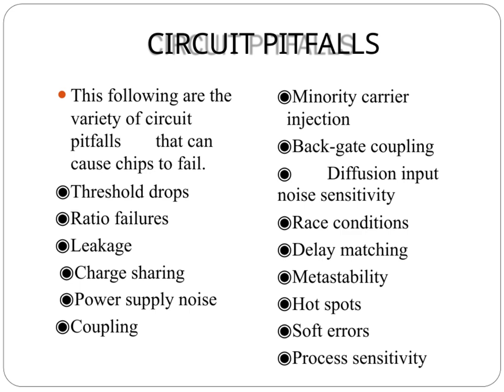Leakage refers to unwanted current flow that causes power loss and potential malfunction. Charge sharing is a tricky phenomenon where charge moves between nodes unexpectedly, disrupting signals. Power supply noise is also a major culprit, as fluctuations can interfere with circuit stability. Coupling, where signals unintentionally influence each other, introduces errors as well.